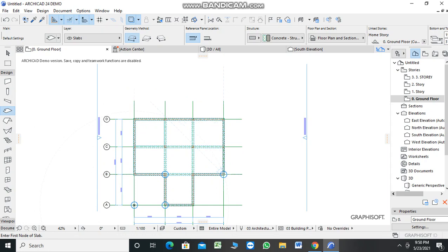So now the specified properties of the slabs are also provided in our tool panel. So we now have to create the slabs also over the ground floor, the top of the ground floor that is connecting to the first floor. So we select all these floors and the outside corners and cover all this and accept this left side panel and create the slabs for this.